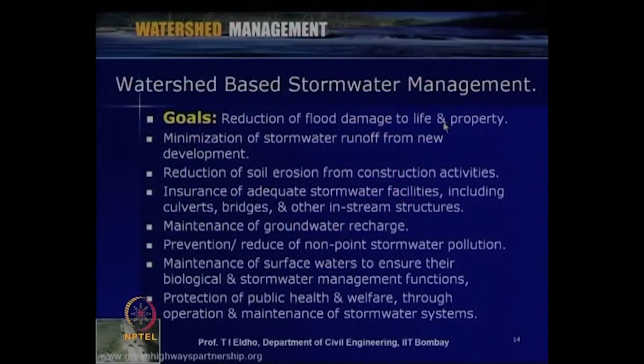So, as we discussed, it is better to do all these practices on a watershed scale, since the watershed is the hydrologic unit, as we were discussing in our lectures. When we look at stormwater management on a watershed basis, some of the important goals include reduction of flood damage to life and property, as we already discussed, then minimization of stormwater runoff from new developments, then reduction of soil erosion from construction activities, insurance of adequate stormwater facilities, then maintenance of groundwater recharge,